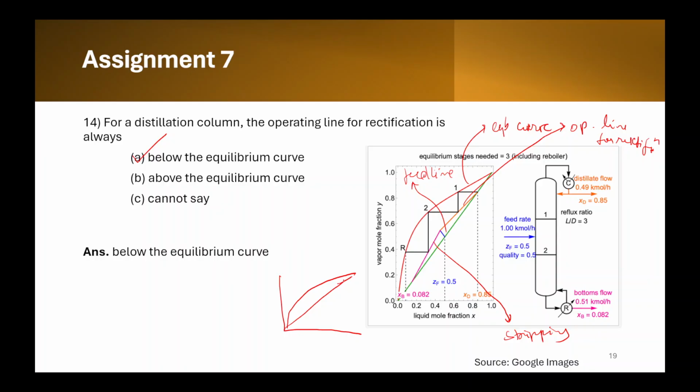this is the plot of, sorry, I'll draw a better one. So suppose this is the xd. So suppose this is the operating line for some reflux ratio. When you keep on increasing the reflux ratio, this slope keeps on decreasing because it depends on this intercept. So intercept is basically xd by R plus 1.